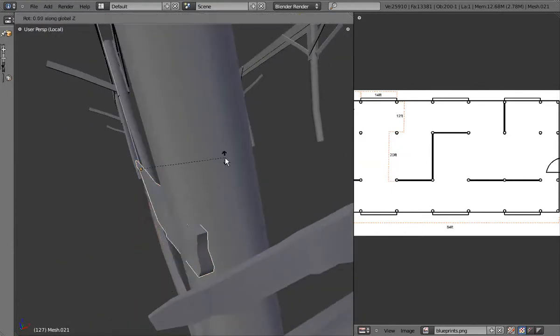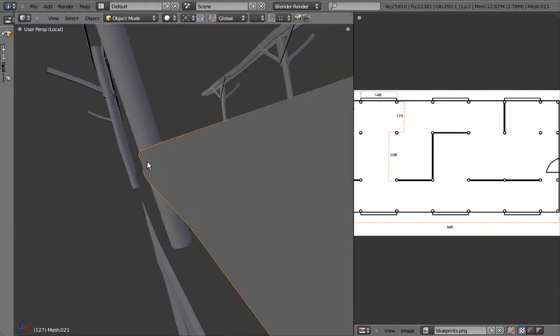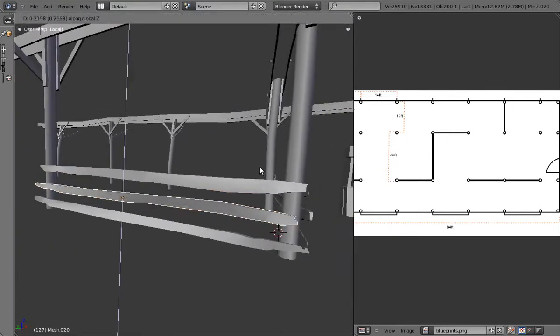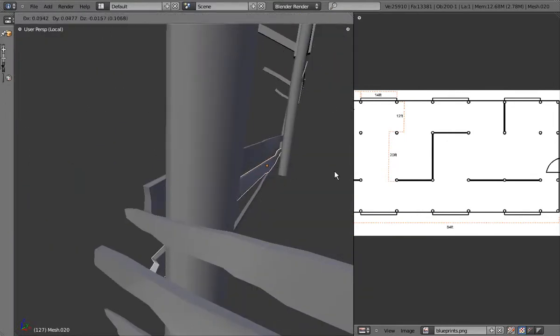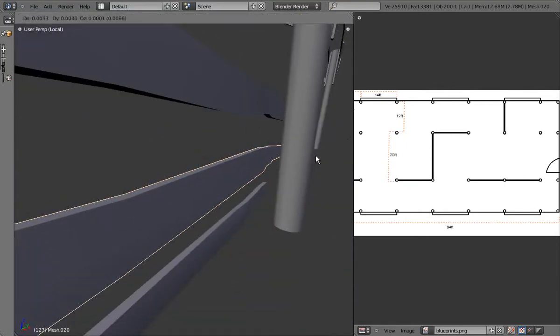I stretch those planks on the side there to cover the span of those 2 pillars, which is a pretty big distance. Later on I end up adding another vertical pillar there, but it's actually going to be just a regular beam of wood, just to create an extra support for the center of these planks.